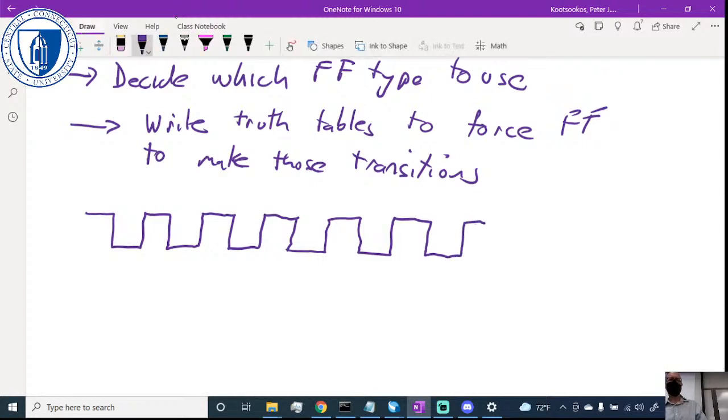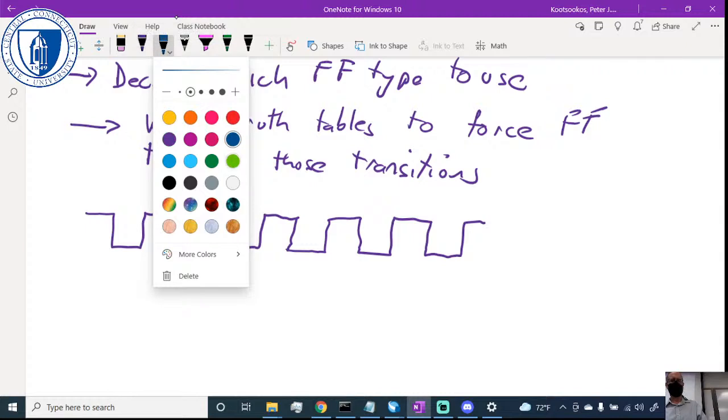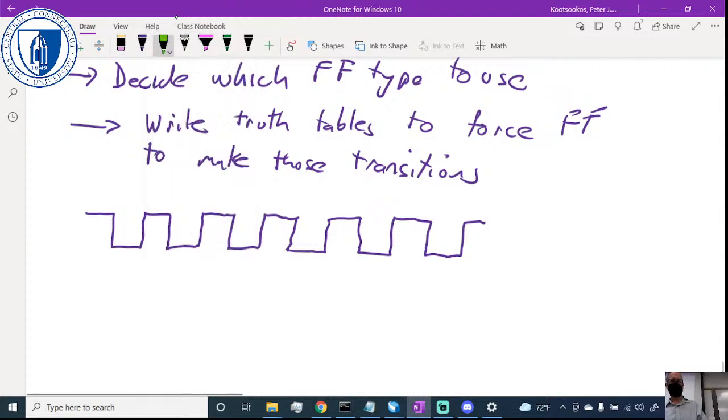The idea is that at some portion of the clock cycle, possibly in the high region, that is when something happens, that the D input is read and propagated out to the Q output.